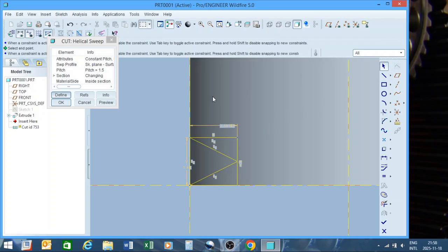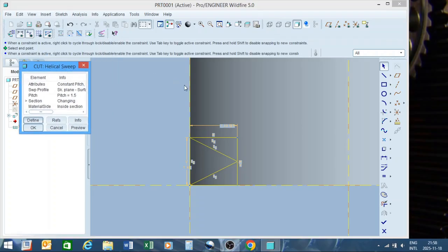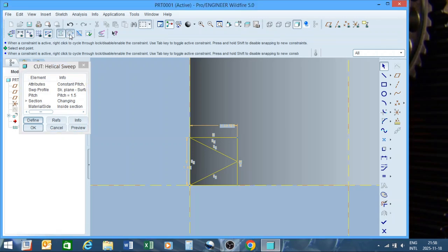we are going to, just another tip by the way, on your sketch feature you have these two little buttons at the top here. If you select these, it will show you an open point, and it will show you if your extrusion is not a complete, closed feature.